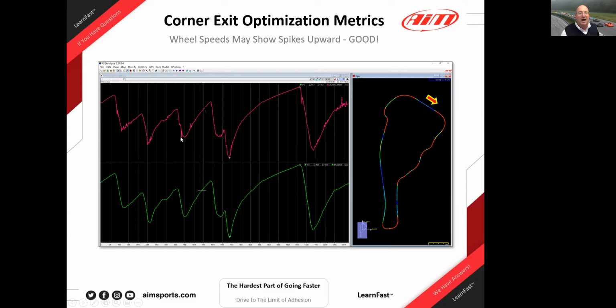It's a sequential box. It's not an issue where it's electronically controlled, so they can't screw it up. But here we see him pushing the brake pedal so hard at the end of the high speed back straight, 160 miles an hour in one of these cars at Road Atlanta, that we see a little bit of rear wheel speed drop there.